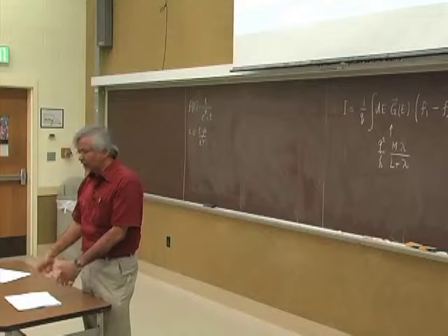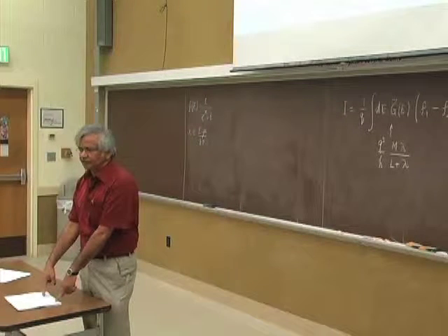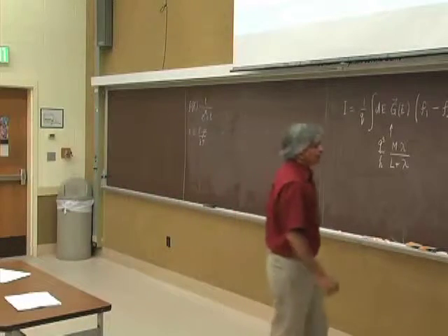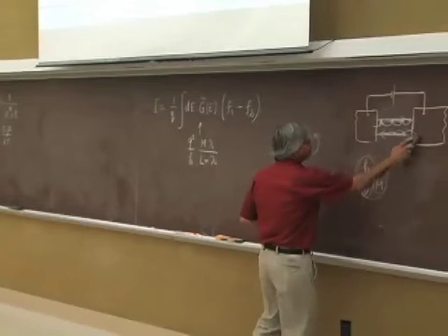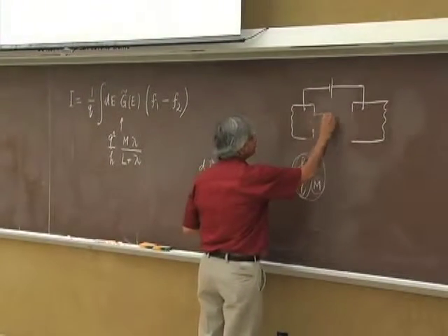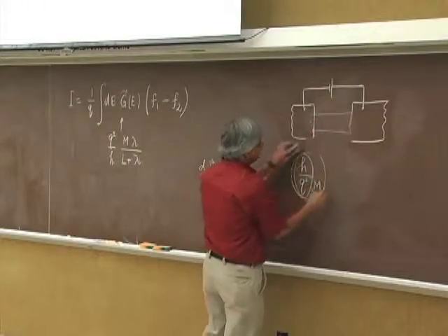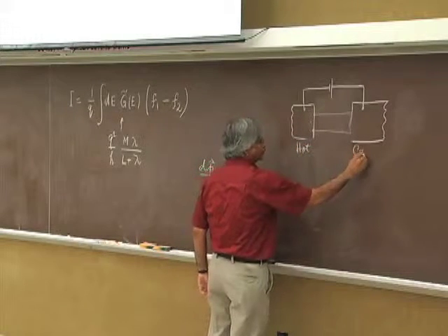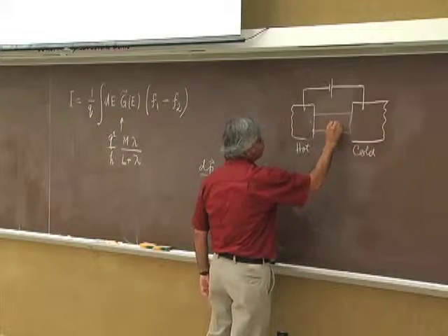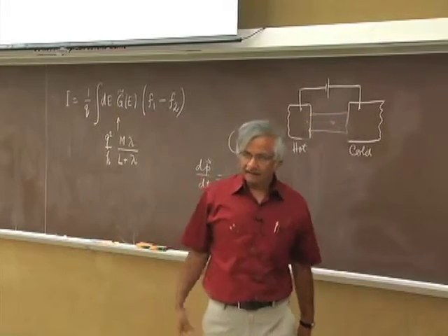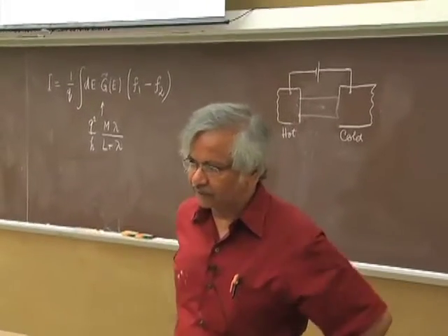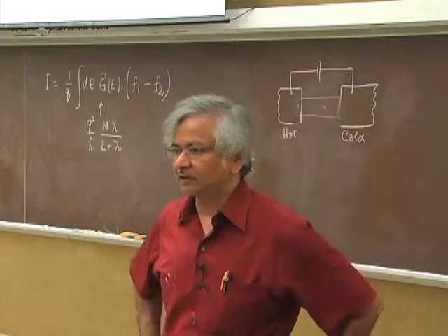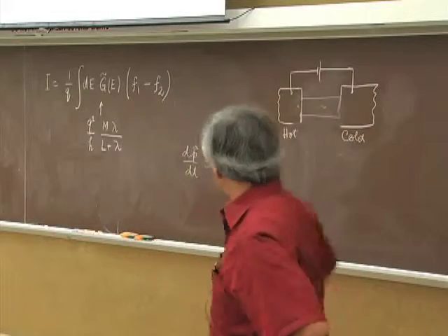Right? Or if you don't allow the current to flow, then a voltage would be developed. Right? So this is the hot point probe experiment. So in this picture, I could say that if this side was hot and this side was cold, then a current would flow in a certain direction. And the interesting point is that the direction of that current is different in N-type semiconductors and in P-type semiconductors. Okay? The question is why?